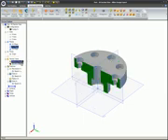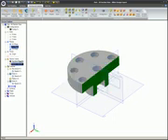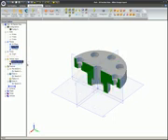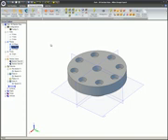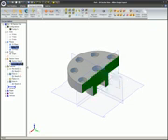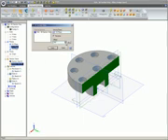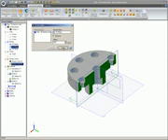If you need to make changes to a section view, if the section is not already active, that is, if it is not in view, right-click on the section in the Design Explorer and click on View. Right-click once again on the section in the Design Explorer and left-click on Edit. Edit the desired values. Click Apply and then click Close.